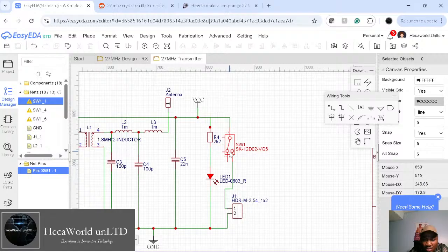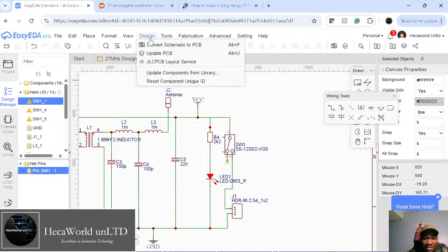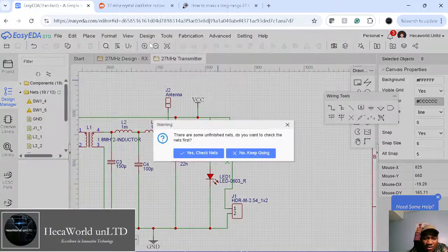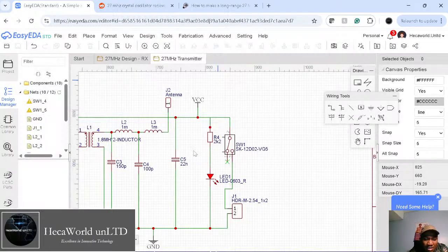So what I'm going to do is connect no connection. I can take a net that is no connection here. This one here says no connection flag. So I'm going to pick that and connect it on that. It tells the system that I intentionally left it open. I don't need to have any connection there. That's why running the check is important. So I'm going to run it one more time and see if I have another error.